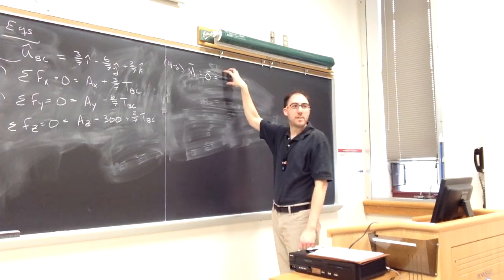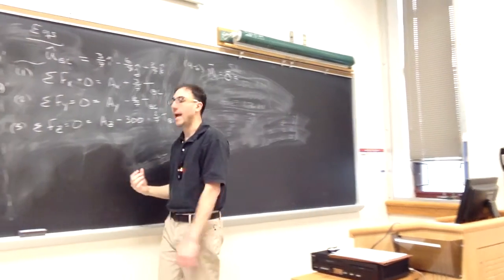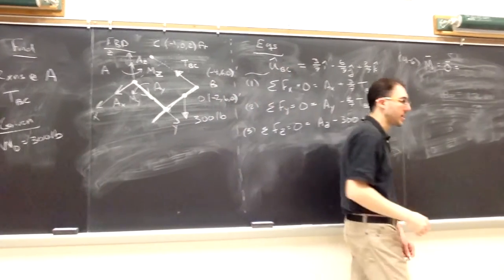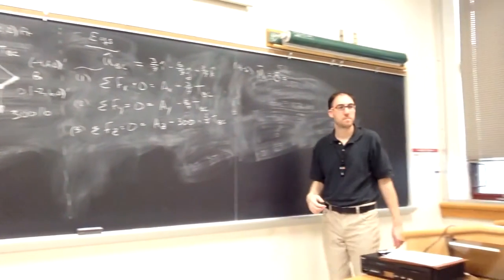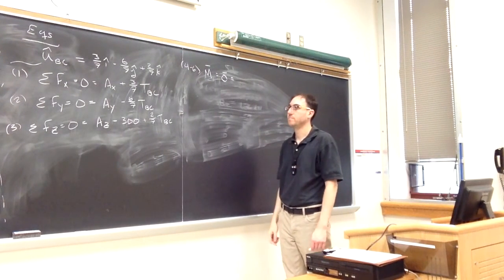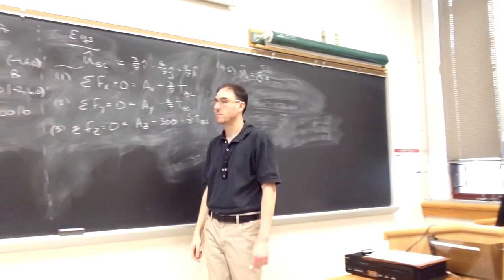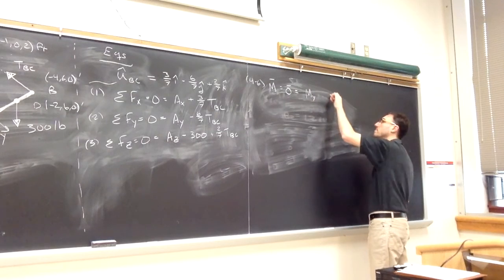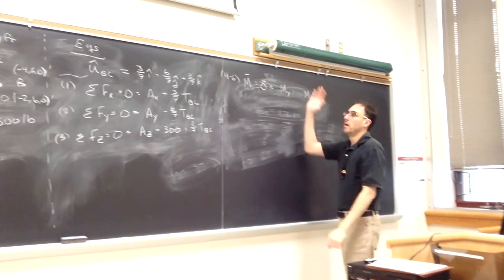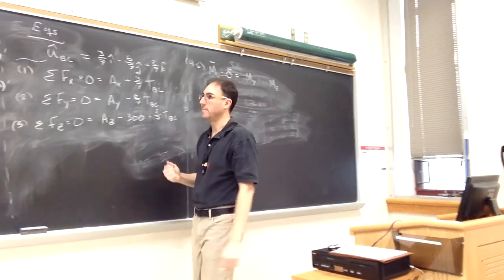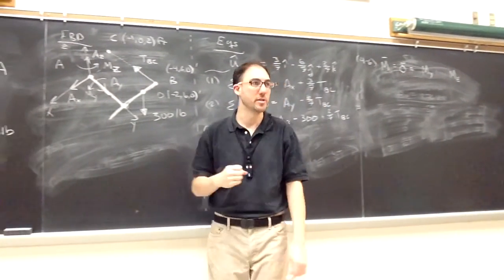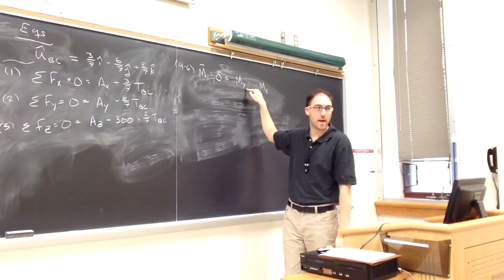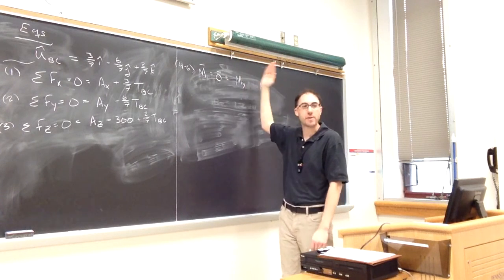When I'm writing my vector moment equation here, I tend to start with any couples that are acting on my object. So in this case, what couples act on the object that we chose to keep? Right, my and mz. What do I need with my and with mz in order to be able to use this in the equation I'm writing? This is a 0 vector. This, as I've written it right now, are scalars. I can't have a vector equal to a scalar.